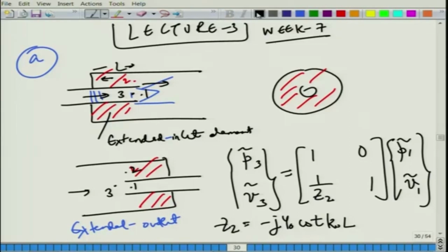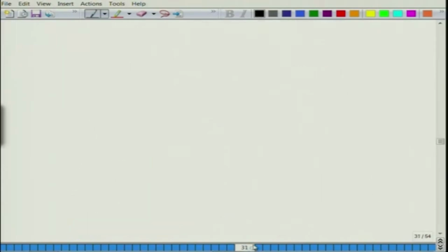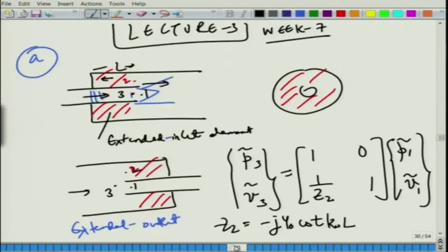That entropy increase only in an approximate manner can be accounted through a parameter, which is again measured or experimentally determined for loss in stagnation pressure for incompressible flows. So, basically at such a point you have, let us say, Ps, the stagnation pressure at point 3, which is just upstream, is equal to the stagnation pressure at point 1, but you also have a loss factor K, half into rho naught into u1, where u1 is the velocity in the chamber. Again continuity will apply, but we will probably come to that later.